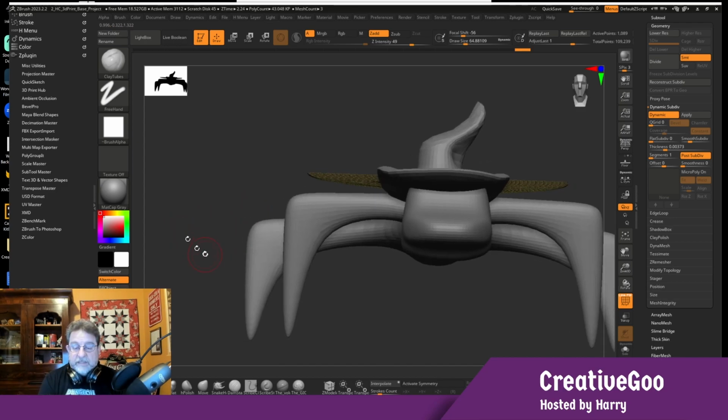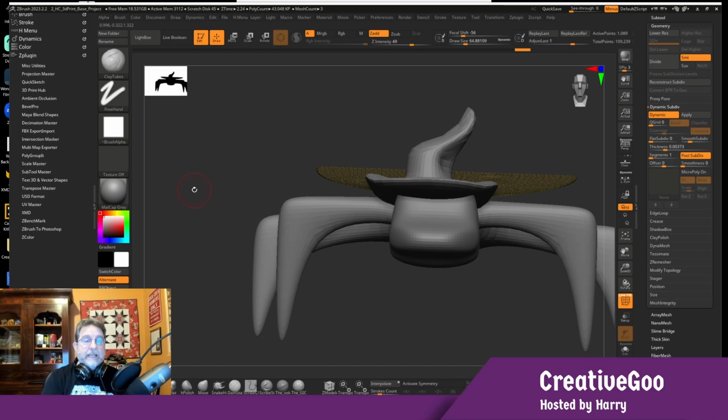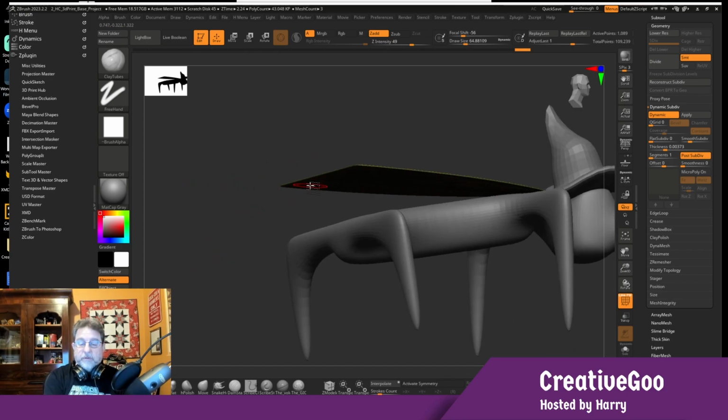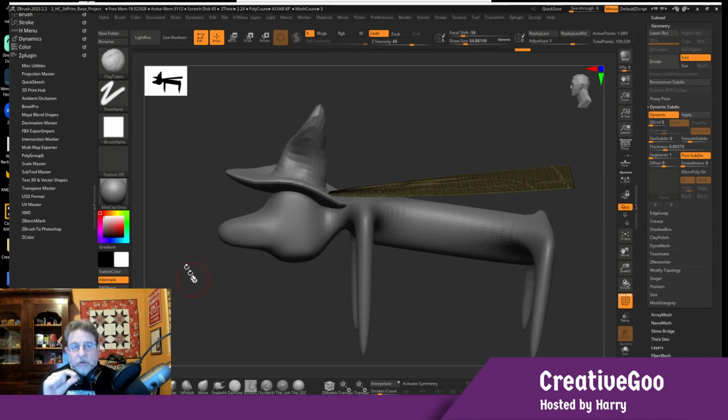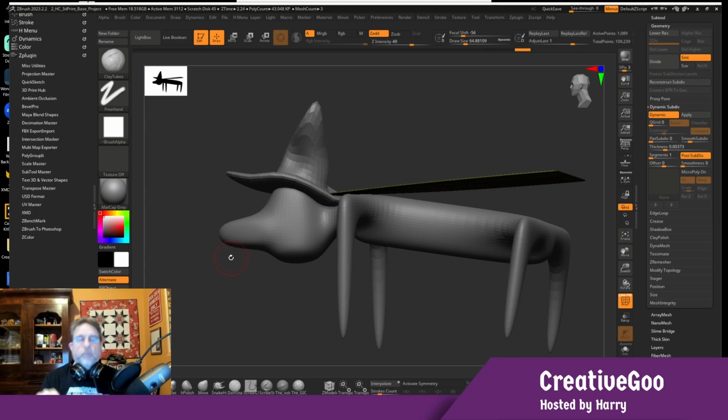So even if I was printing this life size, so the model bigger than my hand, the material that would print that cape would be almost paper thin. So it has thickness, but it's going to break and it's going to cause a print failure. That material might get in the way of other parts of the print. That material may break off in the resin and float around, causing the entire print to fail. So the other thing you have to do is look at a model and ask, is it printable, but also will it print well? And will it survive the process for you to use it for whatever purpose? And so I do have delicate models that I've made.